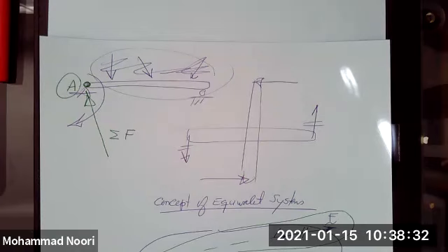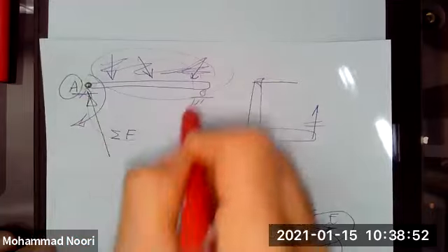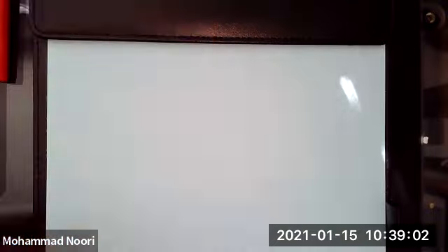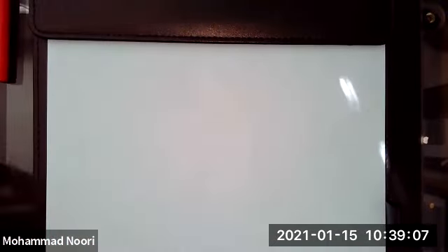So you need to find the moments that those forces that those brackets represent generate about this new location, add up all those moments, and add up all the forces of those brackets and simply move them into that location. We'll see this concept very thoroughly later, but I just wanted to show you what is one of the most important reasons we study couples, because it is through couples that we could demonstrate the action is the same.